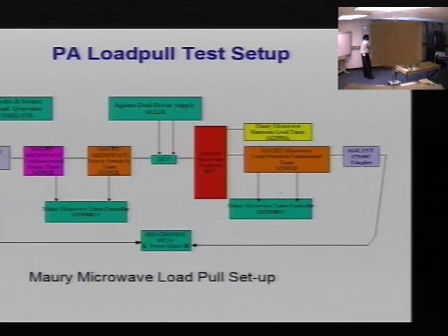The load pull is basically a means for testing the power amplifier, and most of this is done by having tuners at the input and the output. These days they have automated tuners, and these tuners can help you match your output and your input. You can see the fundamental source tuner here, and then the load and the pre-match fundamental tuner there. You have a pre-match and a fundamental tuner primarily because your output impedance is so low that you need to match that to 50 ohms.